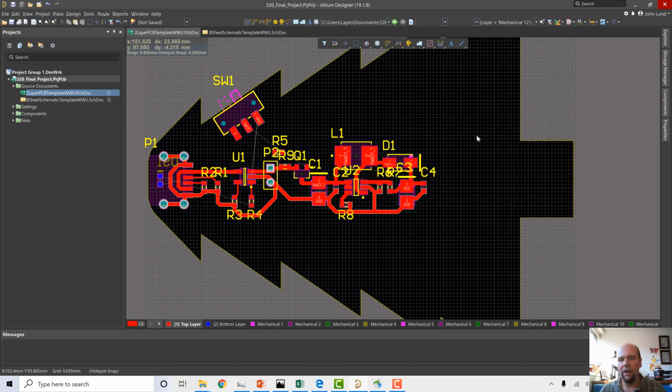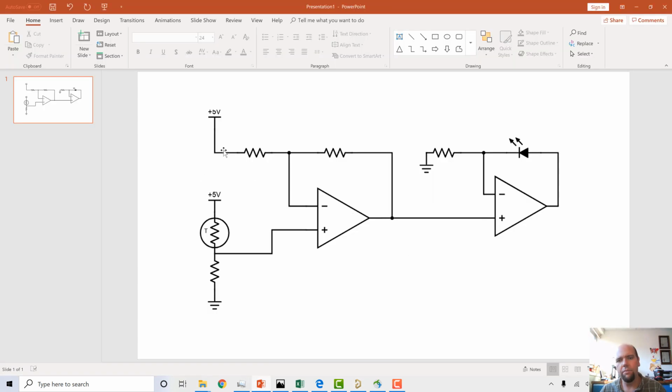So this is really all we have to connect to our final op-amp circuit is going to be this right here. So let's look at what our final op-amp circuit is. My design for this final op-amp circuit, I want to build basically two of these circuits. My design is going to have two thermistors on the corner of the tree. And when you put your thumb on the thermistor and warm that thermistor up, it should turn on a certain color of LEDs on the tree.